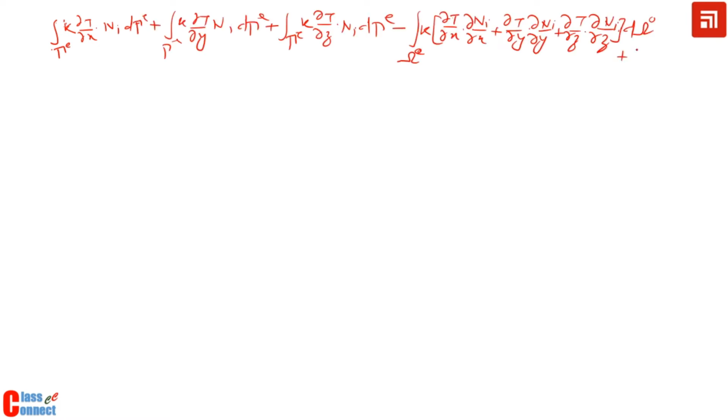So we have the equation, like the area, assuming this kx, ky, kz is the same, so I can write down directly this k del T by del x Ni d area integration plus this q component q Ni d omega, that is equal to 0.